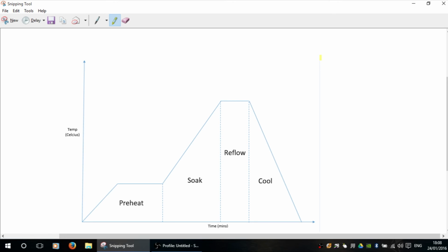One of the important reasons for understanding exactly what it is that you're doing is because you need some sort of appreciation as to how the BGA that you're currently working on responds. And what I mean by that is that not all BGAs are created equally, and some are very, very different from others. Of course, they're different sizes. They're not necessarily different shapes, but they do come in different materials that they're made out of.